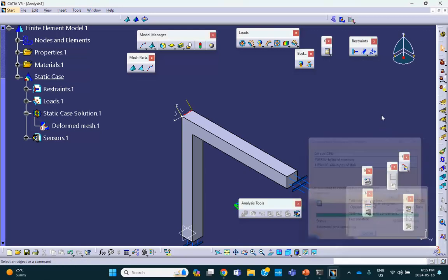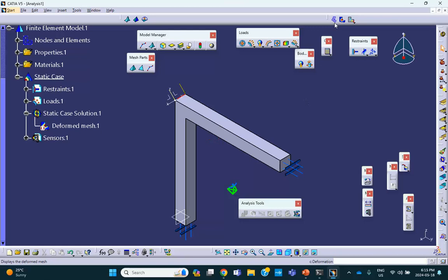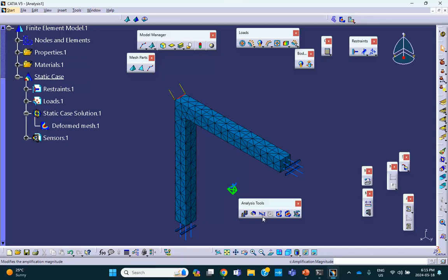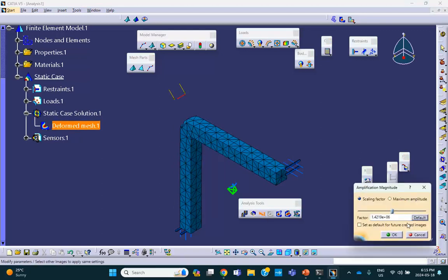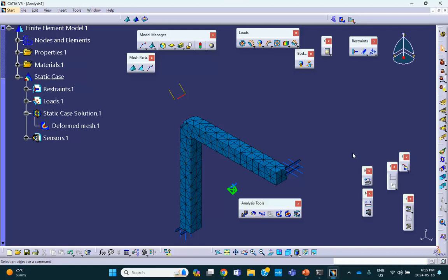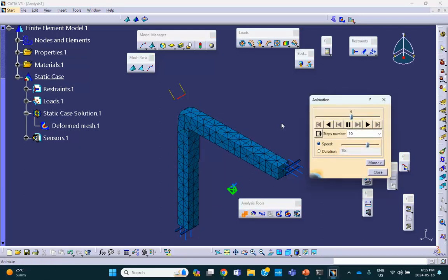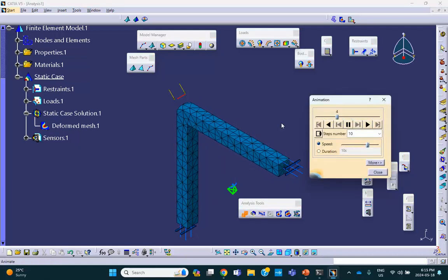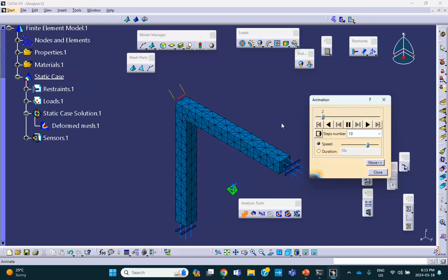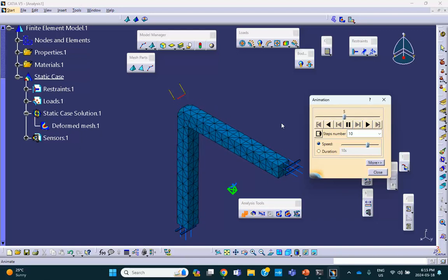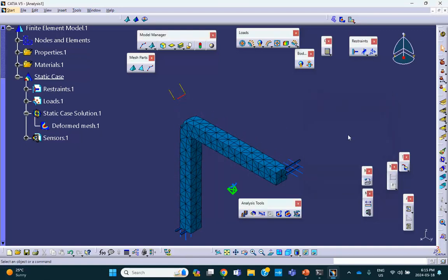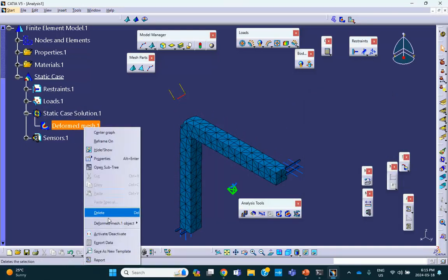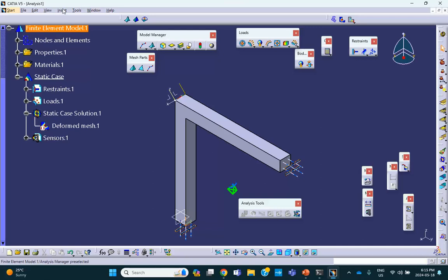And in the event that you want to see the deformation, no problem, but reset your scale. Well, actually plot it, but reset your scale to default. There, nothing magic happens. If you apply 1 pound there, it just makes the whole thing shrink. This is not a buckling. This is just a requirement to do a static analysis with a dummy load. I use a dummy load of 1. You say, fine, no problem. Good. Deactivate.